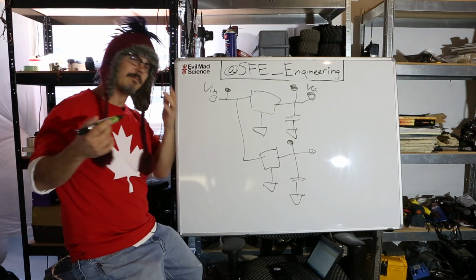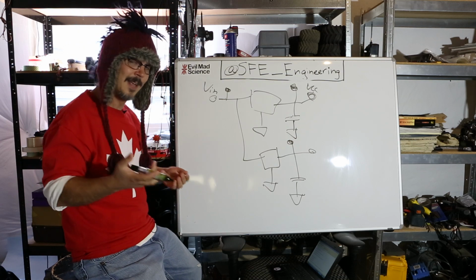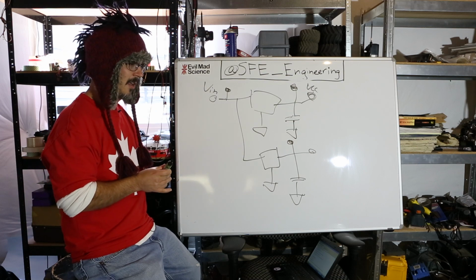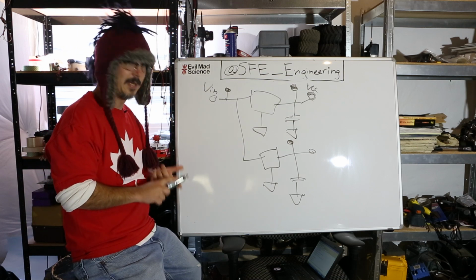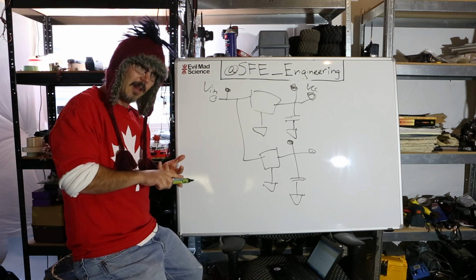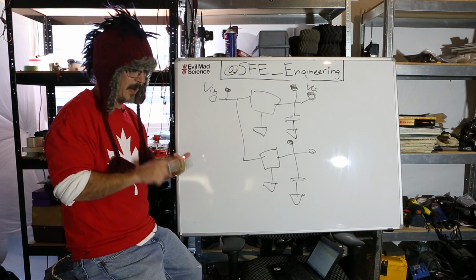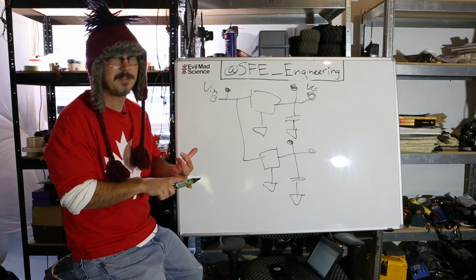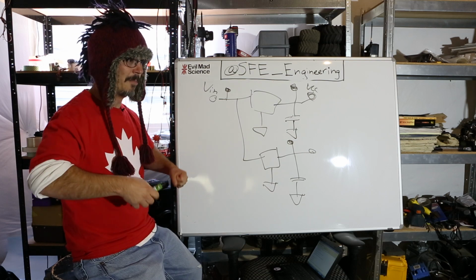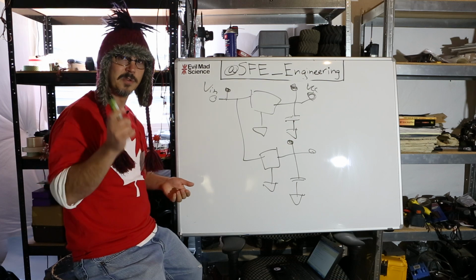You might be monitoring something close to a mechanical part. And I'll tell you something: in all production parts, you are going to have many more mechanical failures than you will have electronic failures. Electronic parts fail, but not as regularly as mechanical ones. Pots, power jacks, screw terminals. Man, I hate screw terminals. Anything that has anything to do with a mechanical force, twisting, pushing, any of it,